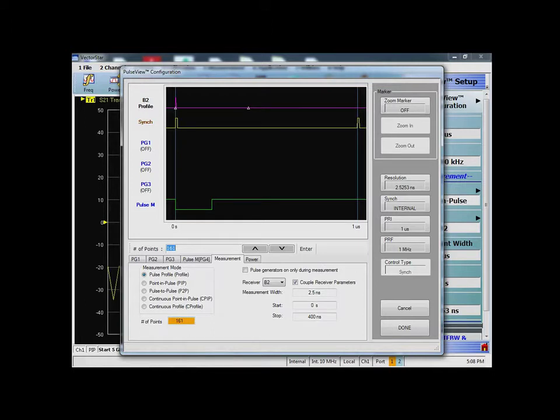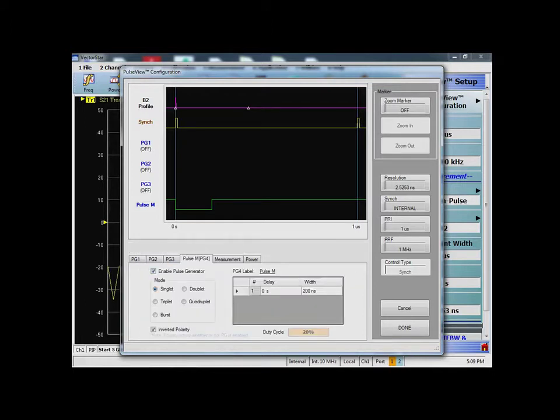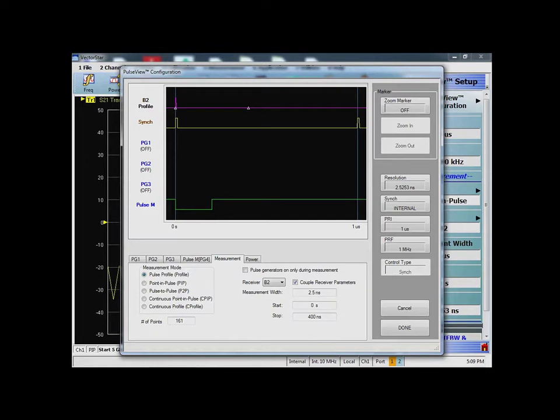Now once that is done, I have fixed my pulse modulation, which is basically happening inside the demonstration module, but I'm using the PGen from the VectorStar to actually help do the pulse modulation. And for the measurement window also I have catered. So you can see this is pretty cool. Why?